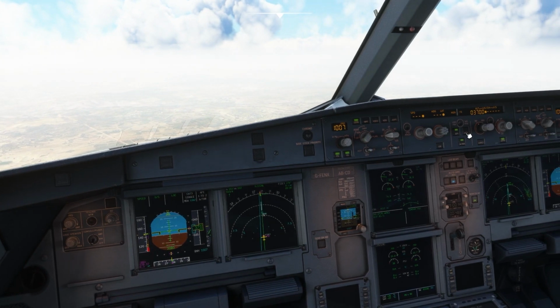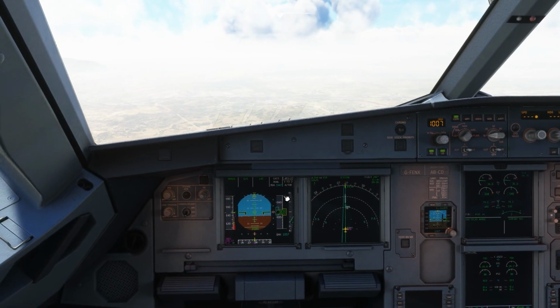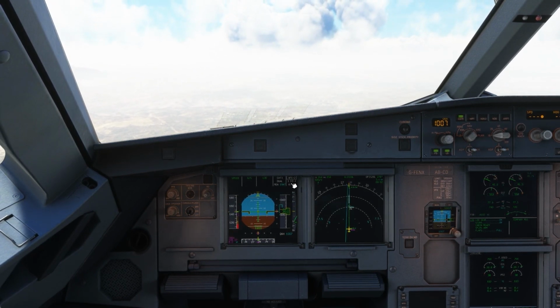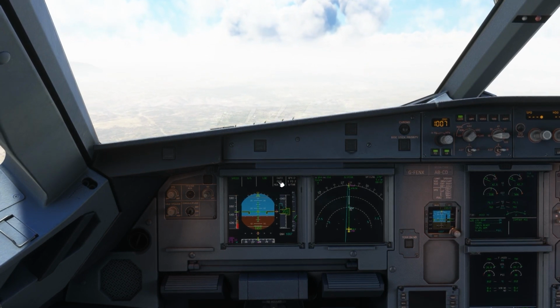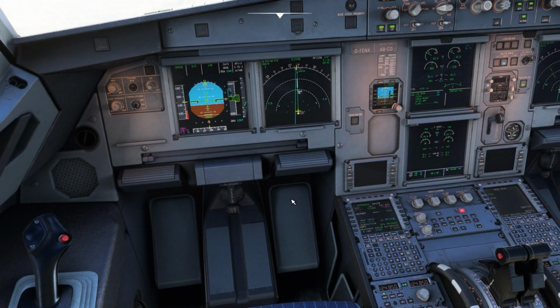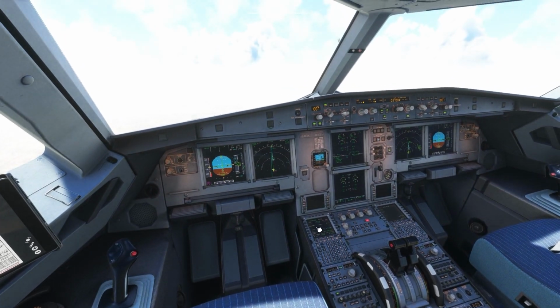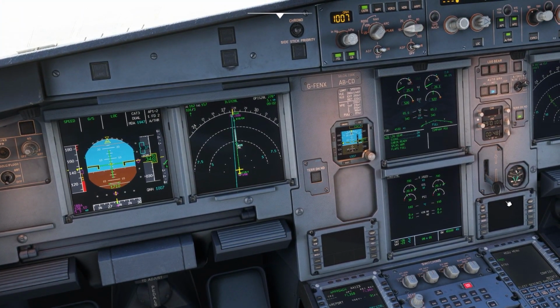And once I press autopilot 2, now you can see both the autopilots are active at the same time, and over here AP1 plus 2 is coming, and CAT 3 instead of single, it's now dual, which means that both of the autopilots are active, and right now I can take the flaps to full, and I can lower the gears.